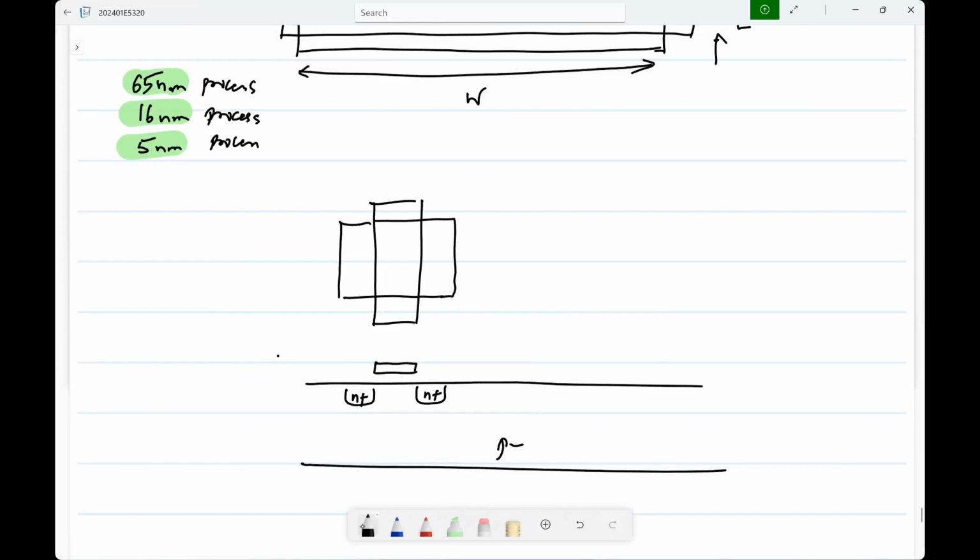If you want to make a MOS current mirror, you need another transistor. Okay. The way you make it is you make these junctions common. Anyway, the current mirror has one of the terminals common, right? The source is common to the 2 transistors.